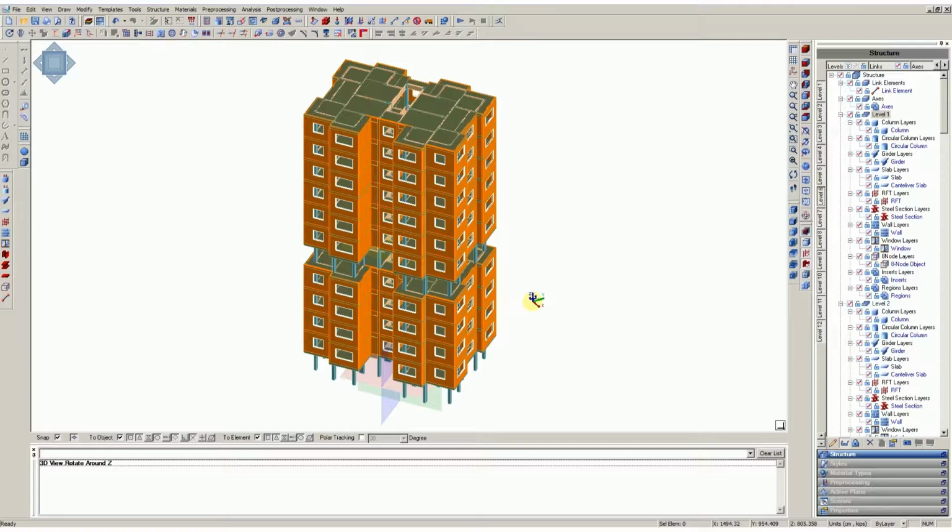In structural analysis, soft story's drift is measured by the angle between the column under loading and the original vertical orientation. An increase in story drift means a higher probability for failure to occur in the soft story. In this example, we will walk you through how to calculate story drift for the entire structure. Let's get started.